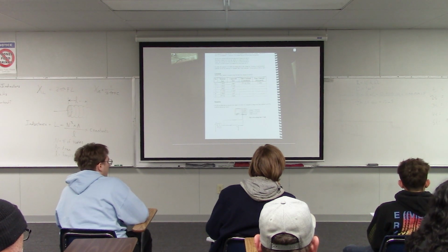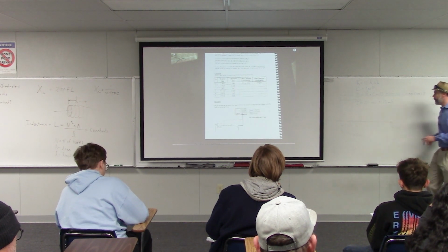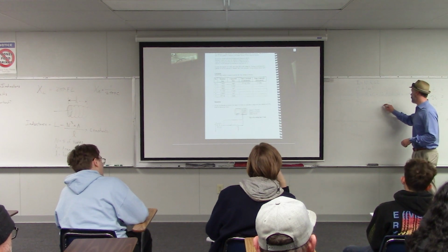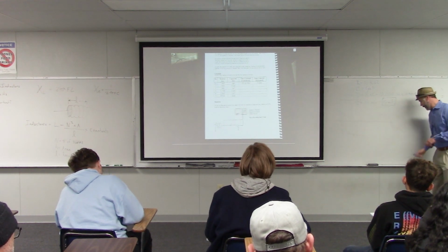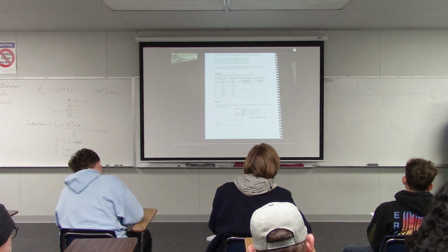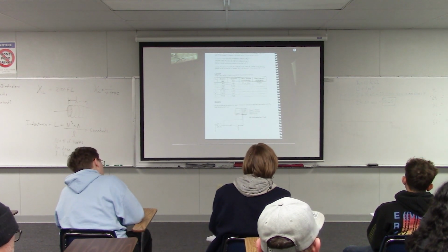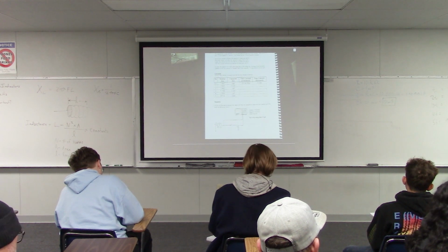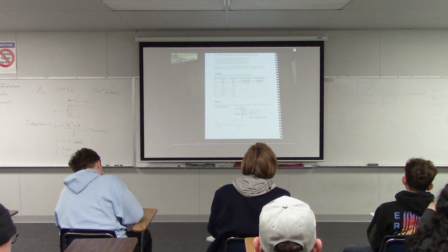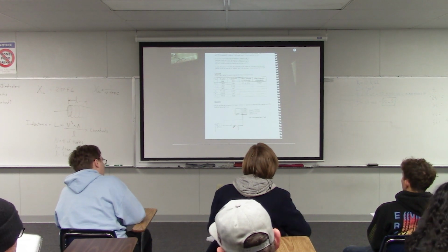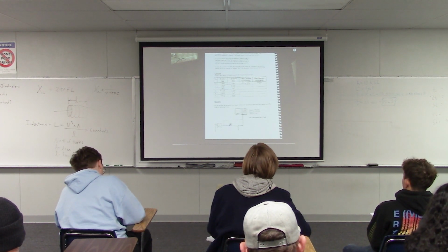All right. So this is the time constant that we have calculated. So 10 milliseconds. So now what we want to do is build a circuit and actually measure this time constant. So we're going to build a circuit that looks kind of like this on a breadboard.